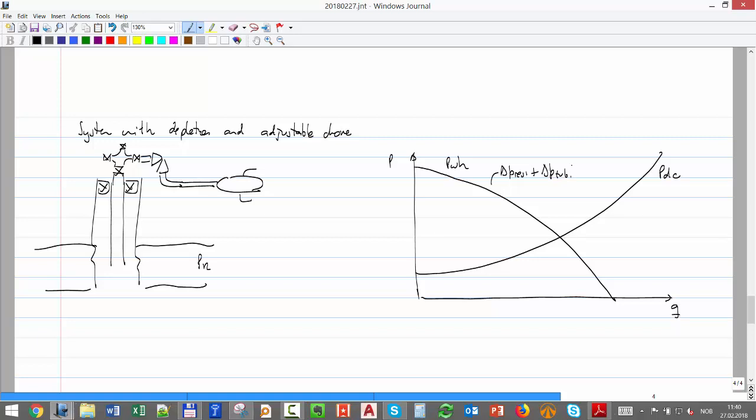Okay, be aware of that. So you have two phenomena happening there. That equation is a reservoir flow equation and has a pipe flow equation. Okay, but with time, due to the decline in reservoir pressure, that curve actually will go down. So that will tell you that in principle, if I leave the choke, if the system has no choke, that will be the rates that I will produce.